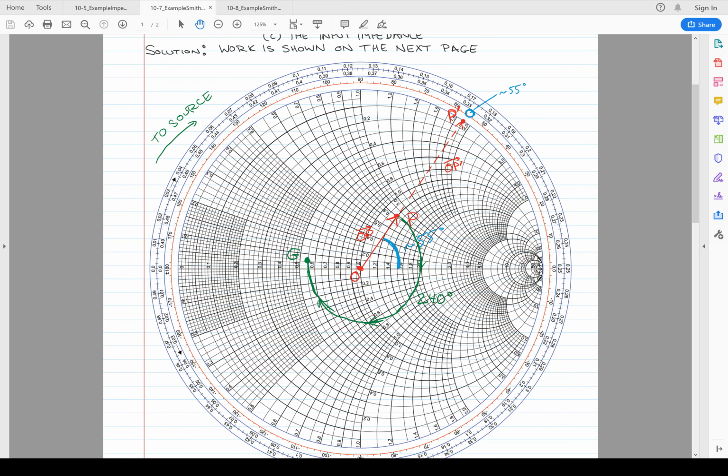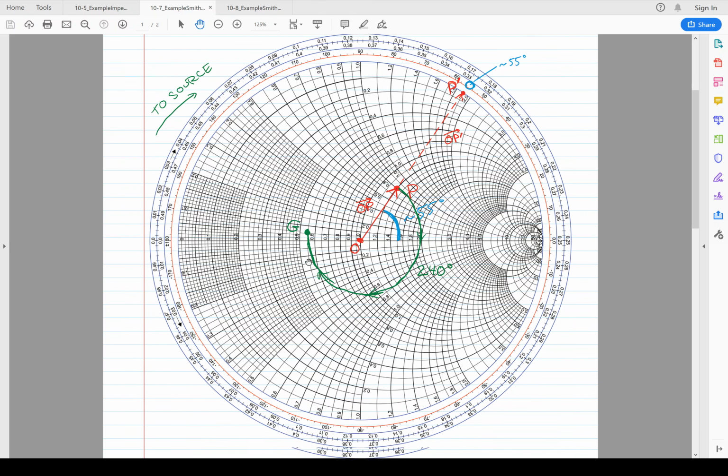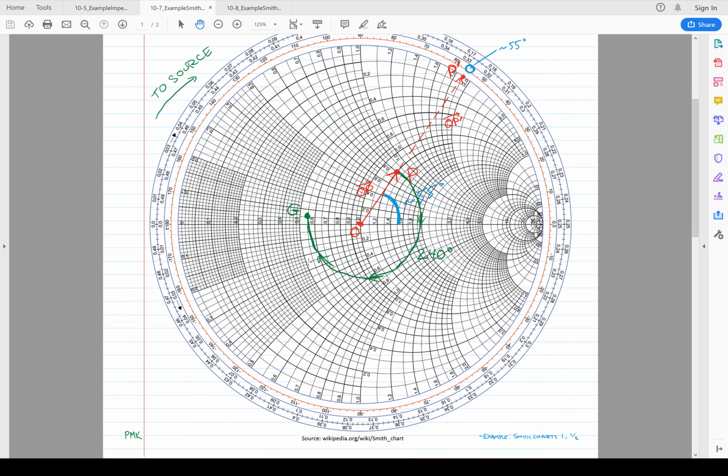They probe the line and move around the line to get the impedance exactly where they want. Instead of measuring and calculating, they put it into practice. They'll see the point P move around on the oscilloscope as the engineer moves around the line. Once you get to the actual input impedance that you want, you're at that location, and that's where you should connect the source.